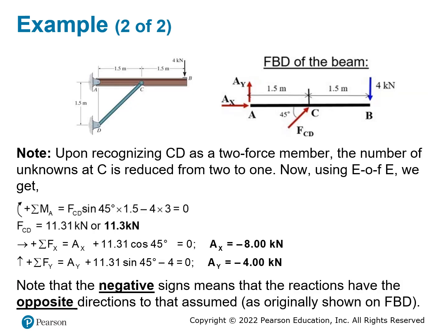And so when you do a free body diagram, this is the free body diagram. This is a 2-force member, so the force is going to be going along this bar here. So you don't need to worry about x and y because you know exactly the direction of the force. This is F of CD, and it's going to be applied to the point C. For point A, it is a pin, so you have two supporting forces, AX and AY. You're going to draw these two.